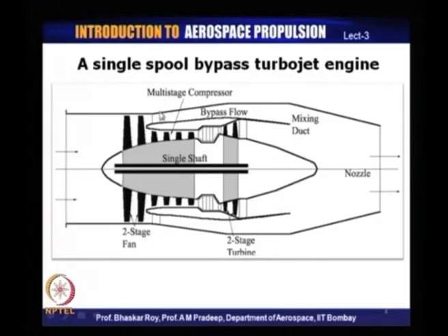The concept of propulsive efficiency has been brought into the picture, that this bypass mass undergoes a small change in the energy, and then this energy essentially produces a very small change in the thrust. However, here what we get is a mixed up thrust production.